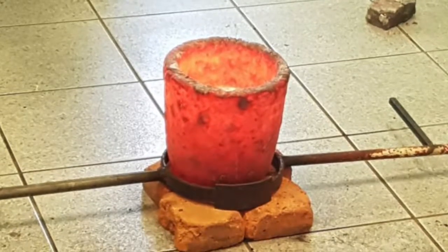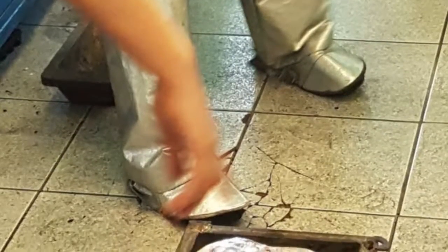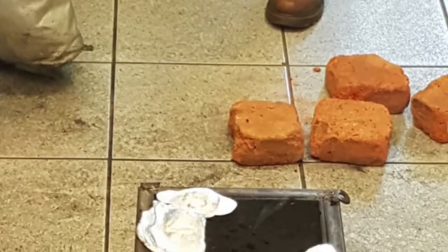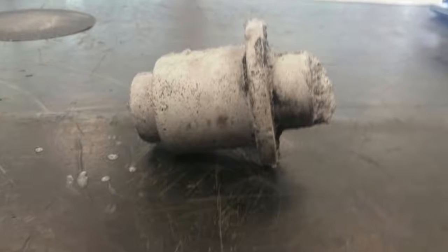So then we create a path from the side B in order to pour the melted aluminum and create escape holes in order for the gases to escape. Then we pour the aluminum into the molds until the material flows through the other side. Then we wait until the aluminum solidifies for about 30 to 40 minutes. And finally, we take out the pieces to start analyzing the impurities and other defects that can occur by the solidification.